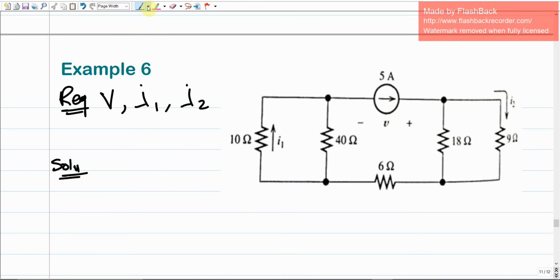So the solution procedure is going to be the same. The first steps are typically the same: just distribute the current through the electrical circuit. We start from the source as IS, the source current, which is already given as 5 ampere. At node 1, this source is going to be divided into I2, which goes over the 9, and I3, which goes over the 18, and they are collected at this node to recede back into the IS.